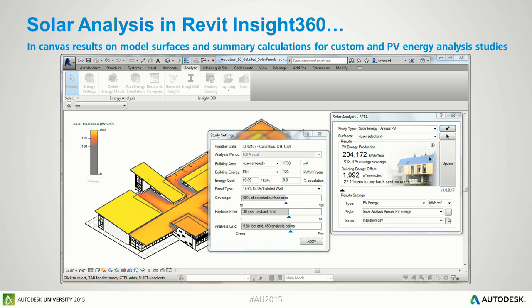And then some advanced settings where you can refine the types of PV panels you've selected. I'll talk about some of these other settings later, but basically if you enter information about your coverage, it's going to assume that the area is not fully covered with solar panels because you need area for access around the edges and roof penetrations.